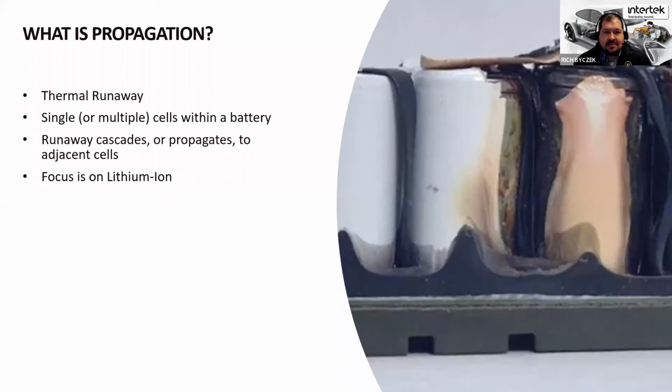This is related to thermal runaway. And thermal runaway is where the heat produced from a cell exceeds the input energy. So this means that even if you remove an external stress such as temperature, fire, overcharge, short circuit, etc., electrical, mechanical, or environmental stresses, the battery will continue producing heat on its own.